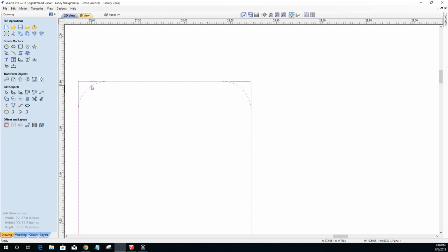I would generally, since it's not going to be too visible, probably do a dog bone fillet if I was cutting this on the CNC, and that way I don't have to screw around with rounding off the corners of my shelf board, and trying to get those corners to be somewhat of a match to those radiuses and things. Of course, I could just run a 1/8 inch roundover bit right on it to round those two edges off on the back side and everything.